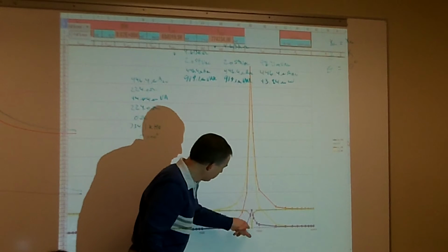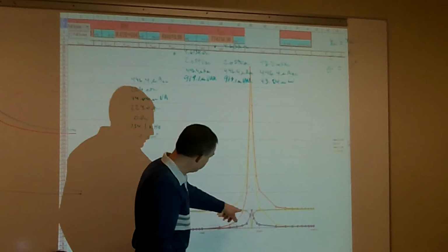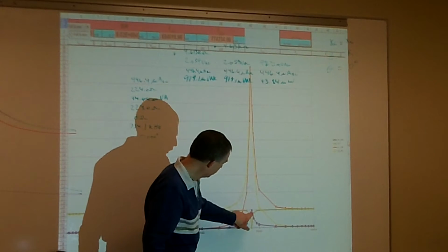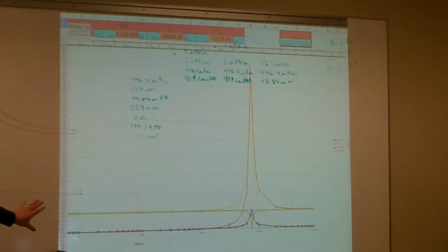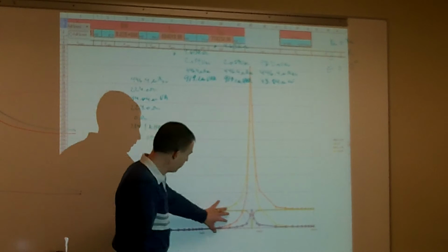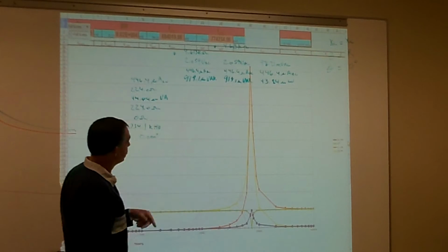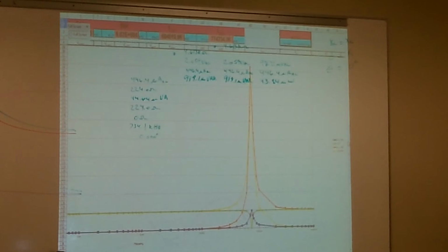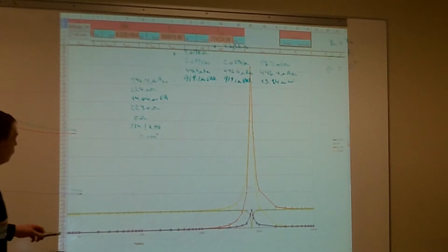One thing about my resonating frequency is, depending on what you have for your inductor and your capacitor, right when I get to this point, a lot of times, if you're listening to some kind of device, all of a sudden you'll hear a high-pitched whistle, depending on what the resonating frequency is. At that resonating frequency, the inductors and the capacitors start to work with each other, and they'll start to resonate. They'll actually start to vibrate and make whistling noises.